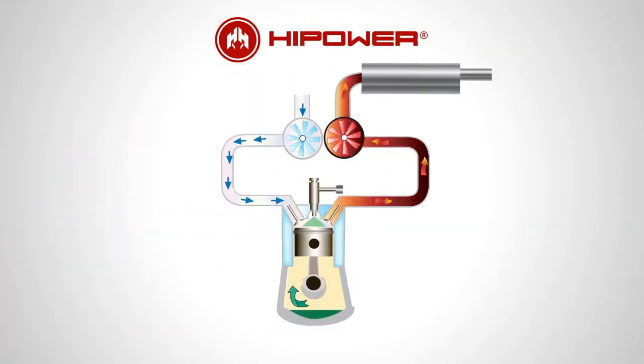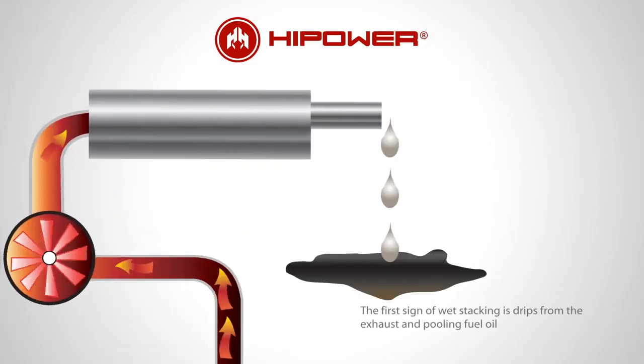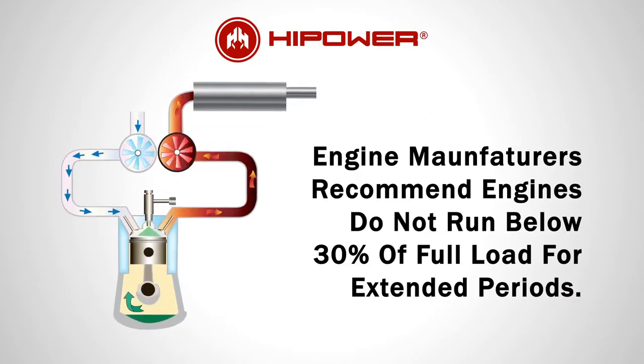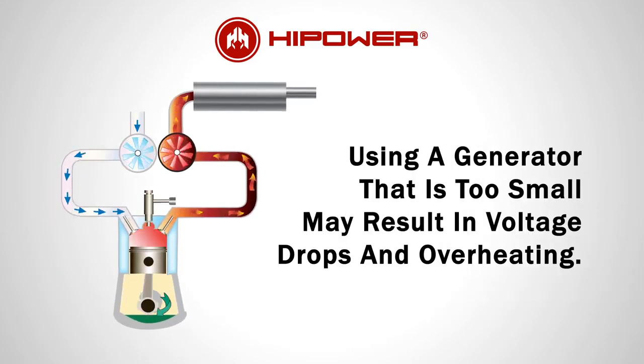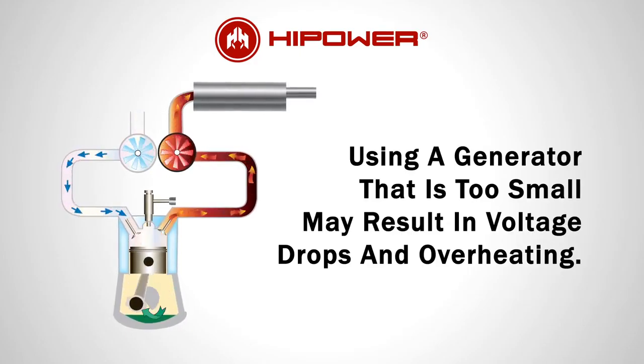Correct sizing of a generator is very important. Light loading can lead to wet stacking and significantly shortened engine life. Engine manufacturers recommend engines do not run below 30% of full load for extended periods. On the other hand, using a generator too small for the load can result in unacceptable voltage drops and overheating.